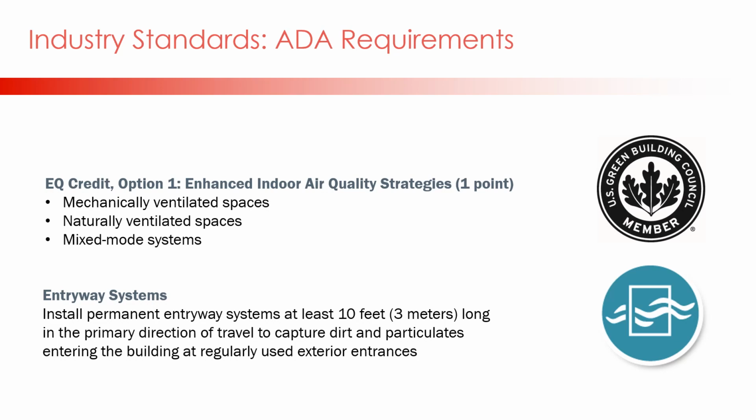Note that while LEED only requires 10 feet, which captures 52% of the dirt from entering a building, to maximize performance, 18 feet is recommended to capture 90% of the dirt, soil, and debris.